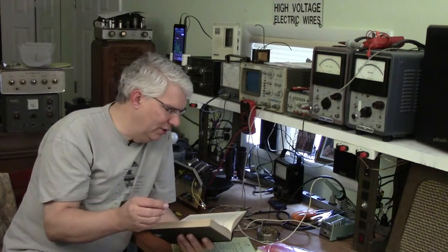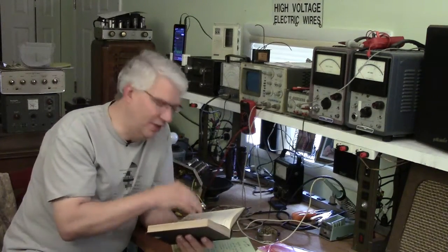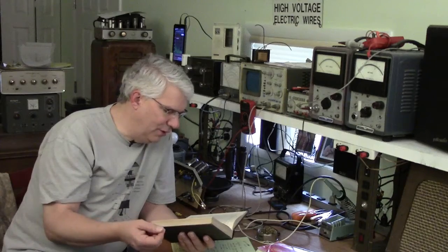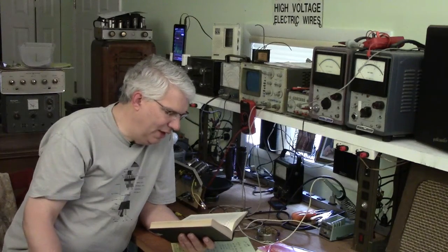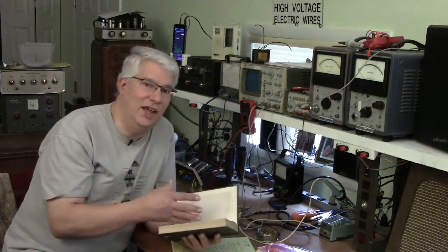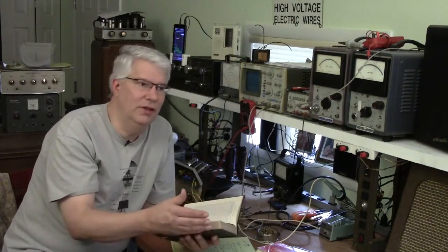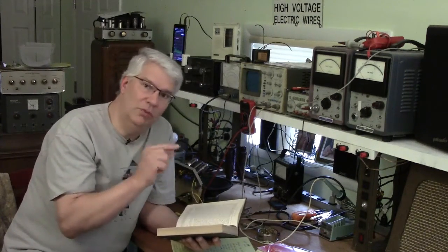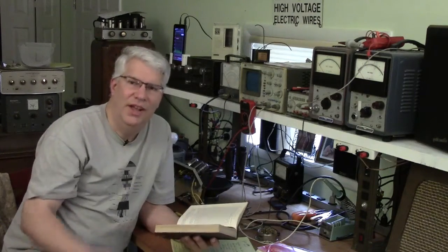Okay, he says practically, however, this function, called f of e sub b plus mu e, whatever, is so complicated in the form of equation 3.2 that it is of little or no value for this purpose. The behavior of a nonlinear circuit element can in general be analyzed mathematically most readily by expressing the alternating current in terms of an infinite power series. So what they go through in this book, because they didn't have computers back then, is they develop the Taylor series expansion of the anode current based on the grid voltage. They spend a lot of time doing that. We don't have to do that, because in this interactive demo I'm going to show you how you can get the same results by just using a nonlinear solver. It's really quite clever.